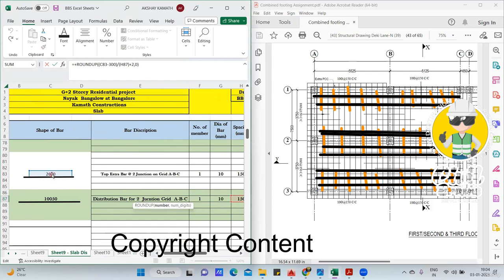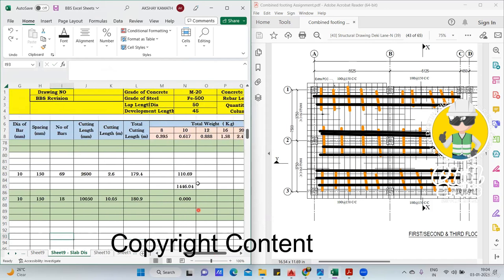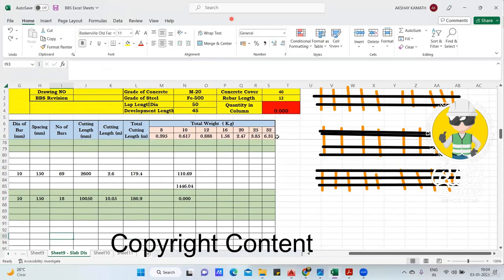This is that 2600. But in that, whatever the beam width is, that is 300, I need to deduct. From 2600, I am deducting 300 here. Okay, getting my point? And then you divide it by spacing. Spacing is 150 and plus 2 has to be done. One span on this side, 1 plus 1 on this side, 1 plus 1 on this side. Finish. Your answer is ready. So in this way, okay, I haven't done the answer.